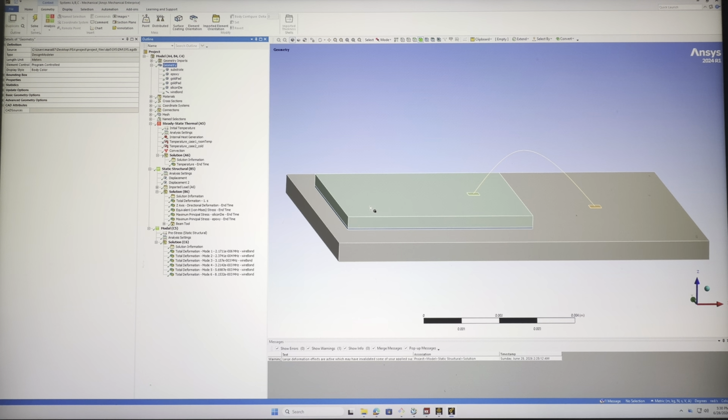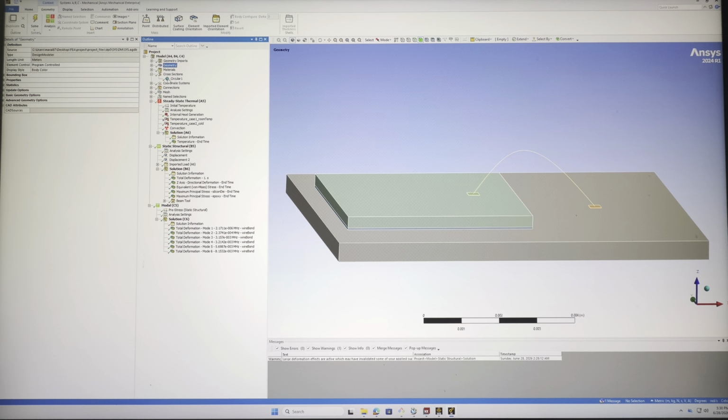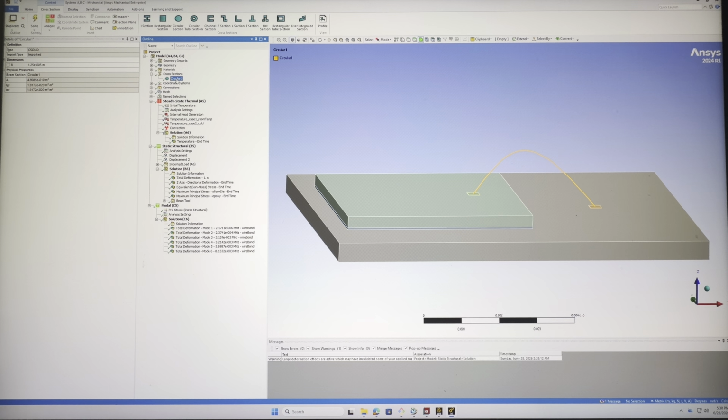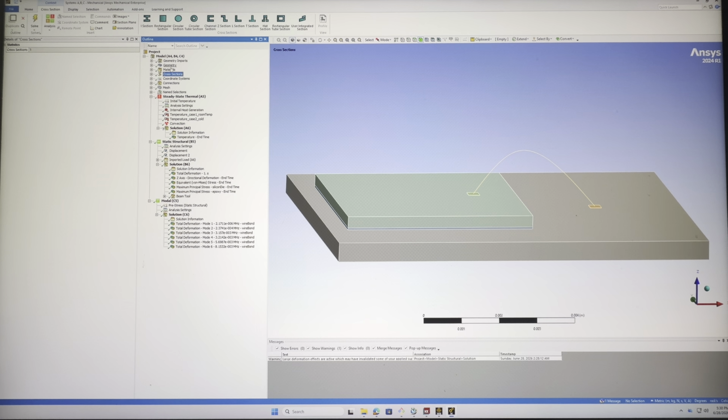So one thing is that the die, the epoxy, and the substrate are all 3D parts. Also the gold pads are 3D parts, but the wire bond itself, I have modeled it as a beam. So I have specified a cross section for that beam, which is 25 microns in diameter. And I have assigned the correct material selections to all of these materials. It is important for this to check the connections inside ANSYS because not all of them can automatically be generated, especially when you have a beam and a 3D element all together.